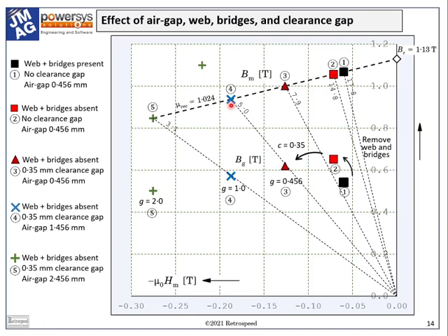The air gap flux density falls to 0.573 Tesla, which is still 5.5% higher than the 0.543 Tesla we started with in case 1, when we were wasting 20% of the magnet.